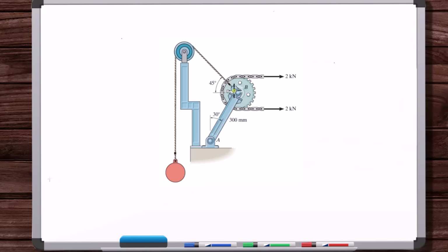Now this would be more involved. You'd have to specify a lot of different accelerations, but if you were doing a free body diagram of this entire system, this is accelerating down maybe, and this has an angular acceleration. You'd have a bunch of different accelerations, but you get the idea. Here, they made an imaginary cut through the chain, but they don't have to put a force here and a moment here. When you cut through a piece of metal, it can support forces in all directions. But because it's a chain, we know that the chain itself as a unit can only support loads along its axis. It's not designed to support loads in any other direction. Loads in any other direction are going to be negligible compared to the main load.